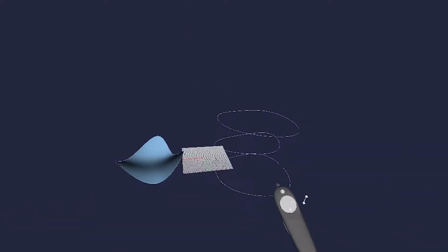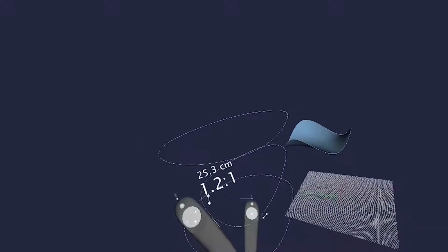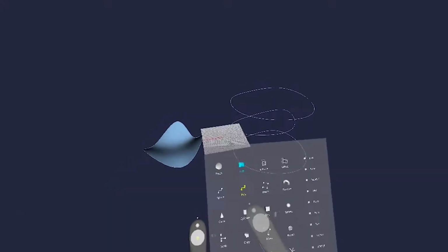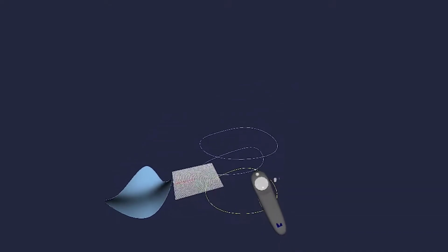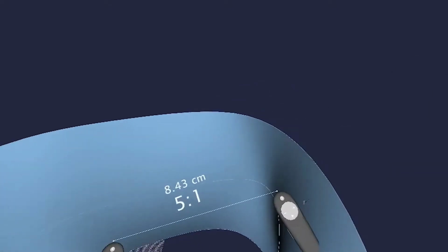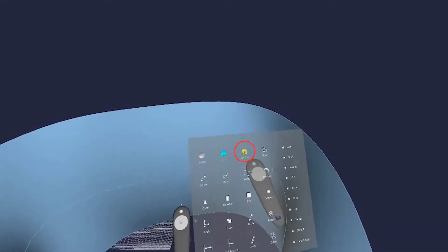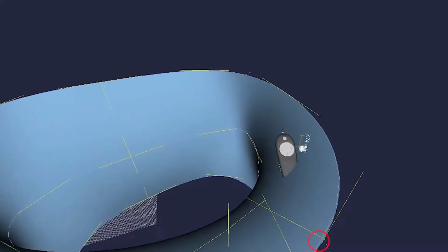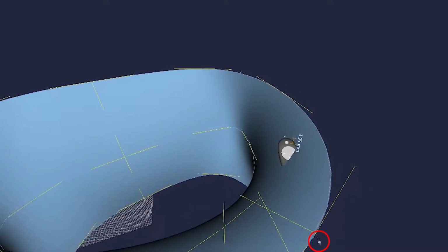There. Now once I've deselected the points, I scroll around to see what the curves look like, and I go ahead and click all 3 curves in the order of which I want to loft them. And then next I'm going to zoom in and perform the offset command, which basically gives the thickness and volume to that lofted surface.